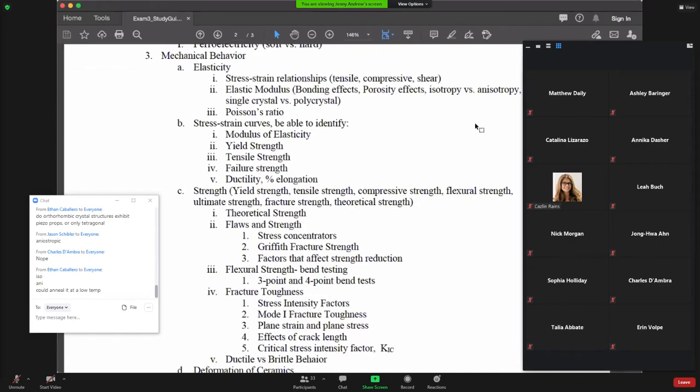And why did you cold work it first? Why didn't you just anneal it? Because annealing normally increases grain size. Yeah. And why then, if you cold work it, I see that Charles has kind of typed the answer out, but why, if you cold work it, does it promote smaller grains?